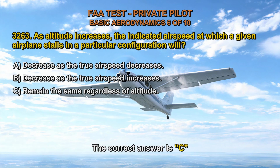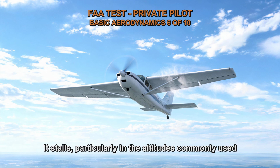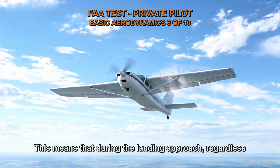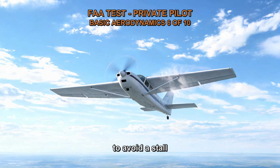The correct answer is C. The altitude at which an airplane is flying does not impact the indicated airspeed at which it stalls, particularly in the altitudes commonly used by general aviation aircraft. This means that during the landing approach, regardless of the airport's elevation or density altitude, pilots should aim to maintain the same indicated airspeed to avoid a stall.